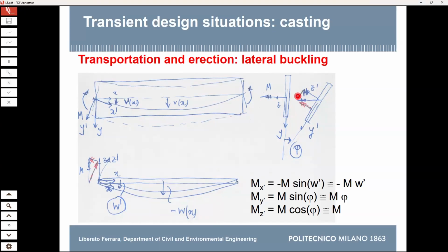That is torsion. So a bending moment which originally was just causing flexural action in the main stiffness plane, as long as the beam just starts to rotate, you just need a little bit. This is also the reason for which we call it imperfection sensitivity. You just need the minimum tolerance and you already have all three of them.